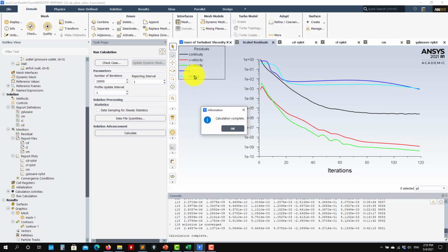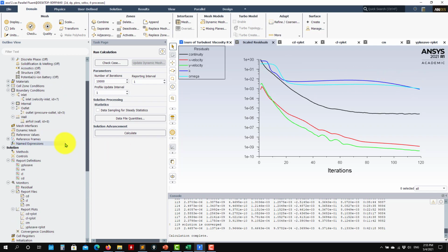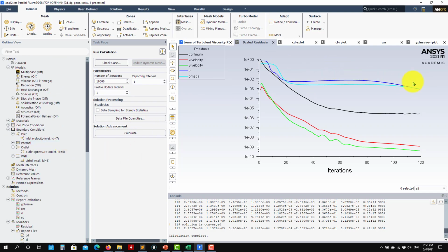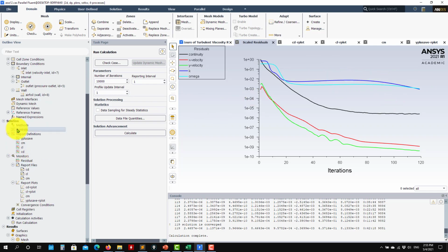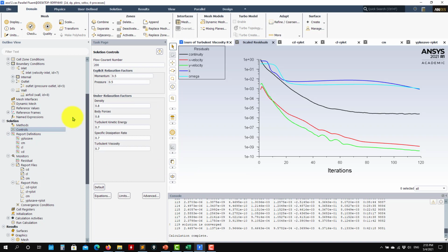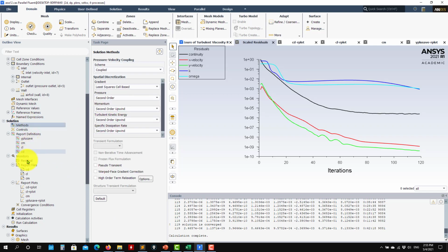See that in this case, the turbulent variables are the ones having problems converging. They have a slower convergence. This is probably nothing bad, by no means, but if you start to have problems, you can go and update the relaxation factors. You might update this.